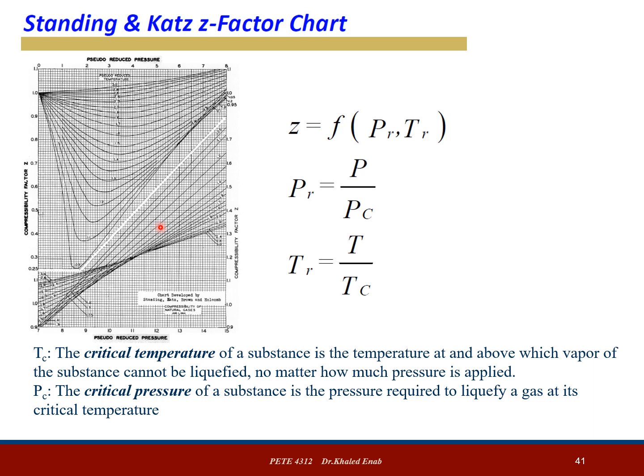Measuring, defining, or estimating the Z factor under different pressures and temperatures became a very important topic in petroleum engineering. Standing and Katz defined and introduced this chart that correlates pressure and temperature to the Z factor, giving the Z factor as a function of pressure and temperature.